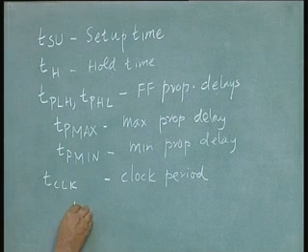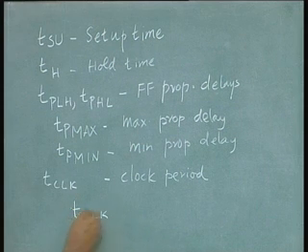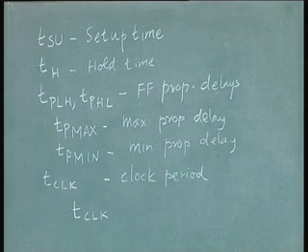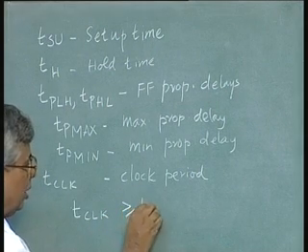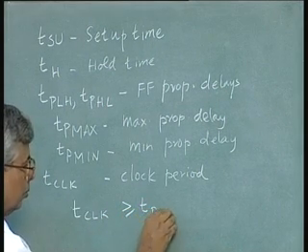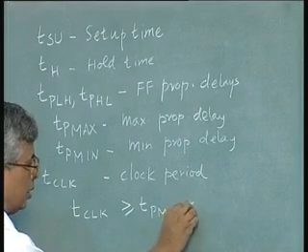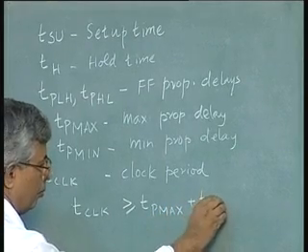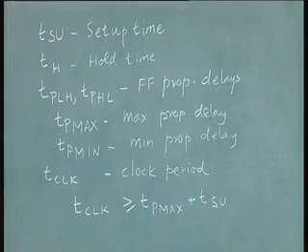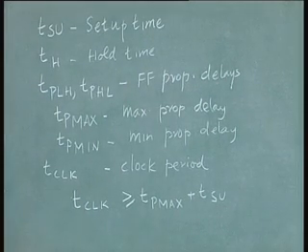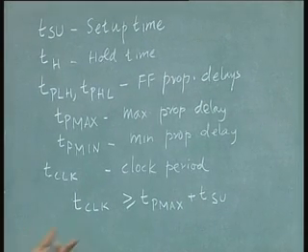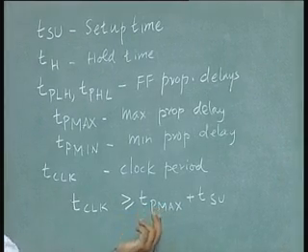T clock should be greater than or equal to TP maximum plus T setup time. Now, you see, naturally this TP maximum need not come into picture.